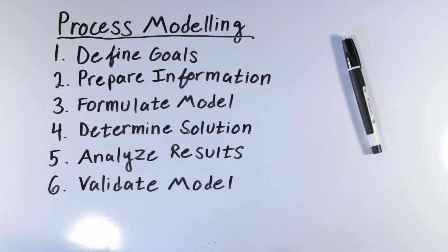Any modeling process can be broken up into 6 basic steps. First is to define the goals. What variables will your control system need to control? Which variables will you need numerical values for, and which ones can be implicitly defined? How does one variable affect another? How accurate does the model of your system need to be?